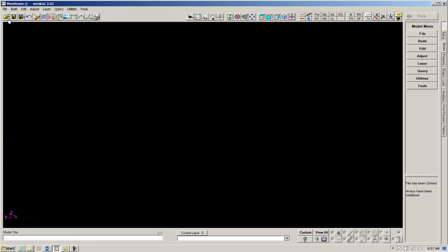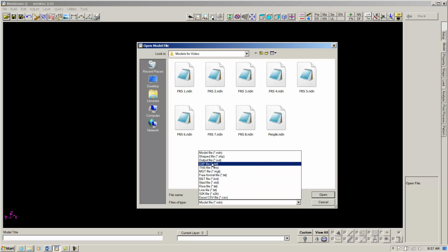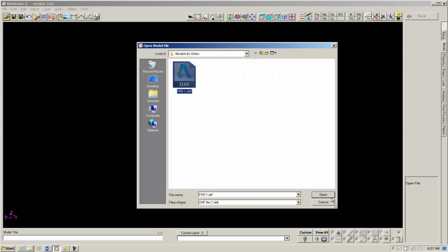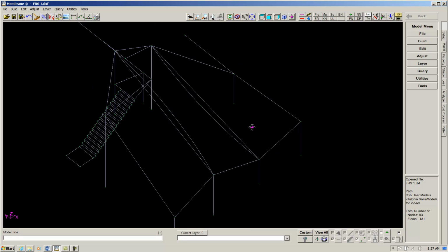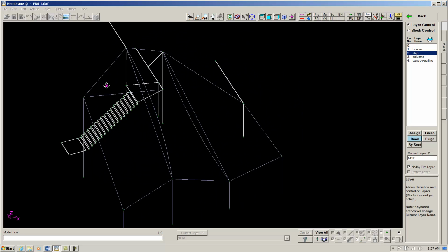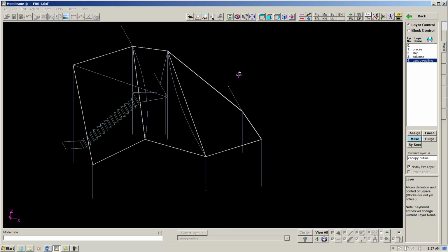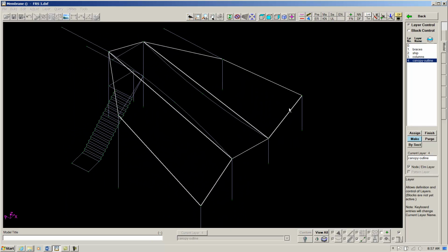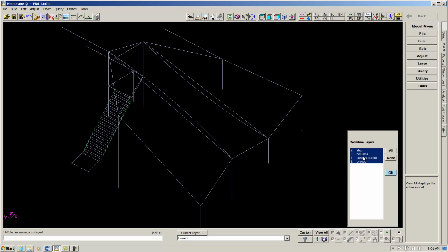The first thing we need to do is define some basic work line geometry. To save time today, we're going to simply read in a DXF file that contains this geometry. This is the geometry representing half of the structure. What's highlighted in white there is part of the ship that's already existing. This represents the outline of the canopy that we're going to be building. The first step will be to generate the element mesh.